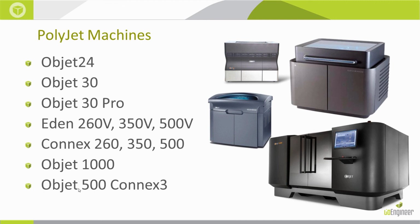I would say the Objet 500 Connex 3 is the flagship PolyJet machine. It's not the largest machine, but it's the most capable machine. It's the same size as the Connex 500, but it has an extra print head. So you can print 3 materials simultaneously. You could do a rigid opaque, a rigid translucent, and a rubber-like material. You can also do full color at the Connex 3 level, and it's the only machine that has the color palette.